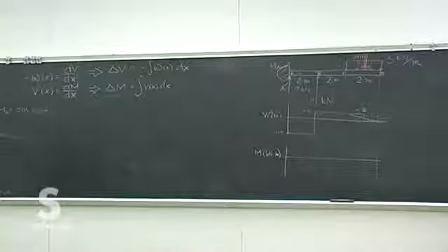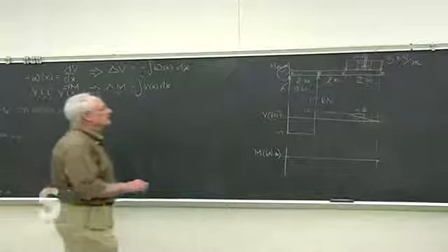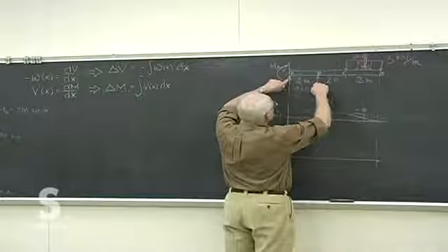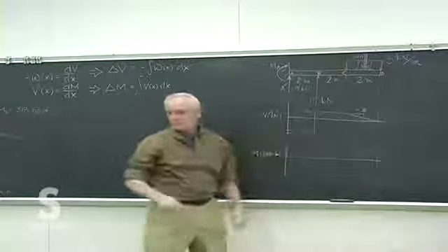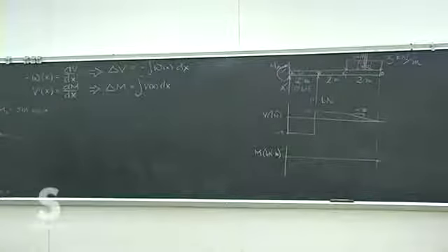It's not zero there because the cantilever support immediately puts a moment in the beam. And you can figure it out by summing the moments about A and using the equivalent point load of the distributed load. Be careful, don't forget that's not actually there.